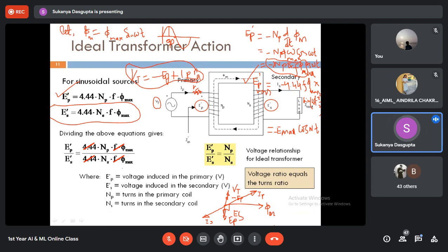We'll see the effect of magnetizing current as well as the effect of magnetic flux in the phasor diagram of the transformer with loaded condition, right? But here in case of an ideal transformer, IP is the primary current phasor and Is is the secondary current phasor. Considering inductive load, a lagging type power factor, the secondary current Is will always be lagging by the secondary voltage, right? So this is the power factor angle.